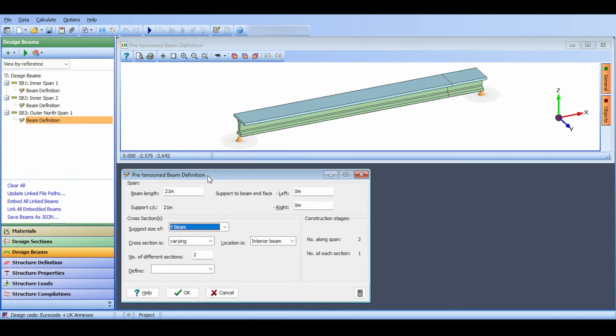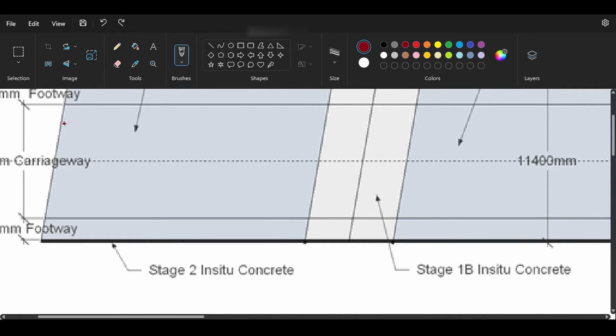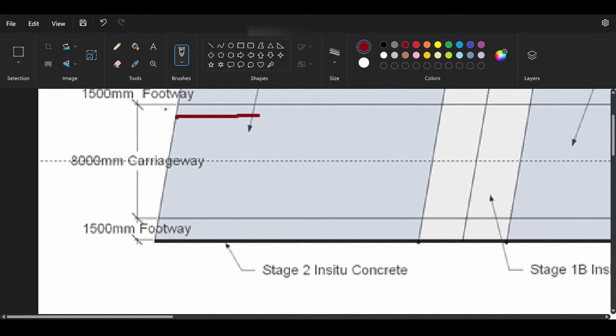Okay, so what do we have here? This is the external slab. I'm talking about this, by the way, just that we're on the same page. I am talking about the beam here on the edge. And by the way, let me tell you the beams we have here. For the carriageway, I will have a beam here and a, let me see, it's 8 meters, right? Let me just check. This is 8 meters, so 1 meter here and 1 meter here, 6 remains. So 2 meter spacing, meaning 1 and 1. Those are my beams, yes.